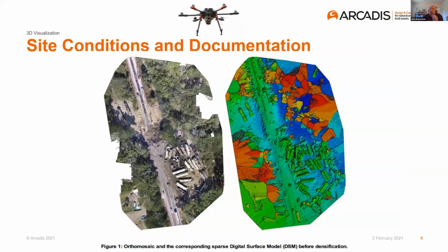how we have a surface orthomosaic model that can be generated from stitched imagery. This is a train derailment. You have a standard photo on the left, but we can also do a variety of manipulations depending upon the camera on the UAV itself. And the photo on the right, you can see, is a generated digital surface model that is a 3D representation, and it can also do topography, which can be really useful in evaluating response activities that may be limited due to steep slopes and other site characteristics. Next slide, please.